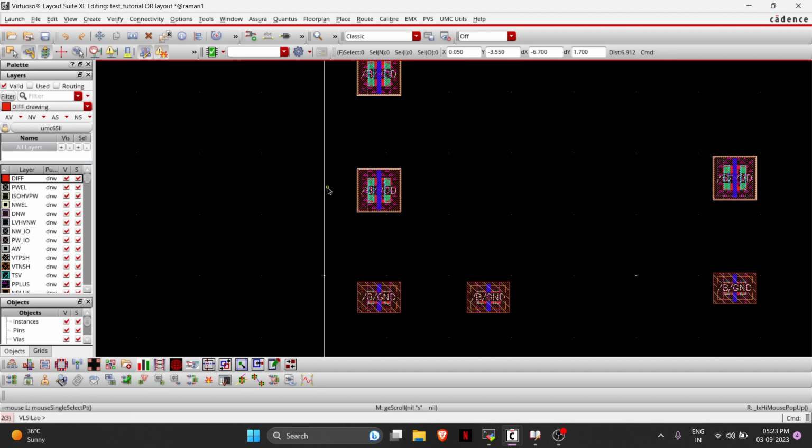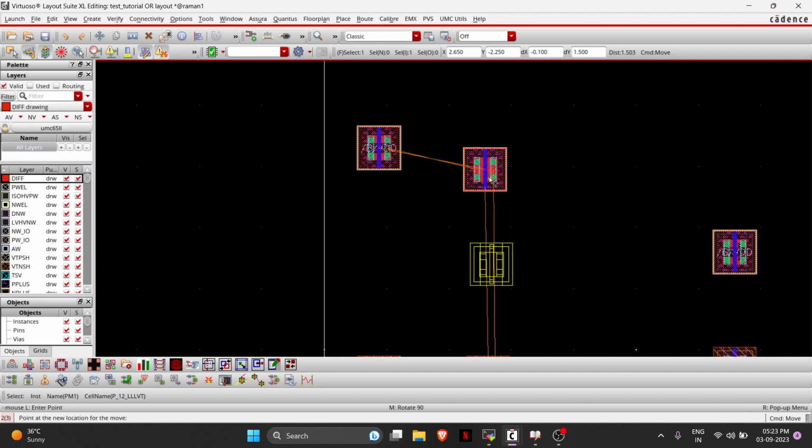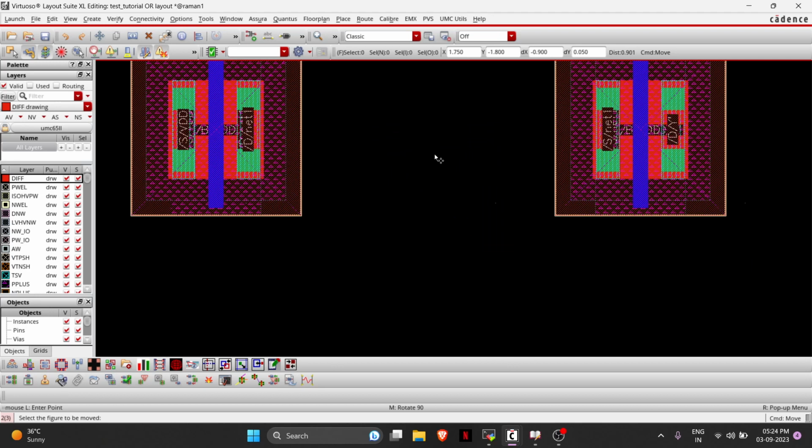Now this is the main thing. We need to avoid placing these two transistors far apart. So you can change this setting to freely move an object around. It is not always preferred because when you are making a symmetric design to copy elements from one block to the next, it's better to keep this alignment perpendicular so you don't accidentally shift up and down and drag in one direction. But if you want to make it more speedy, you can do this.